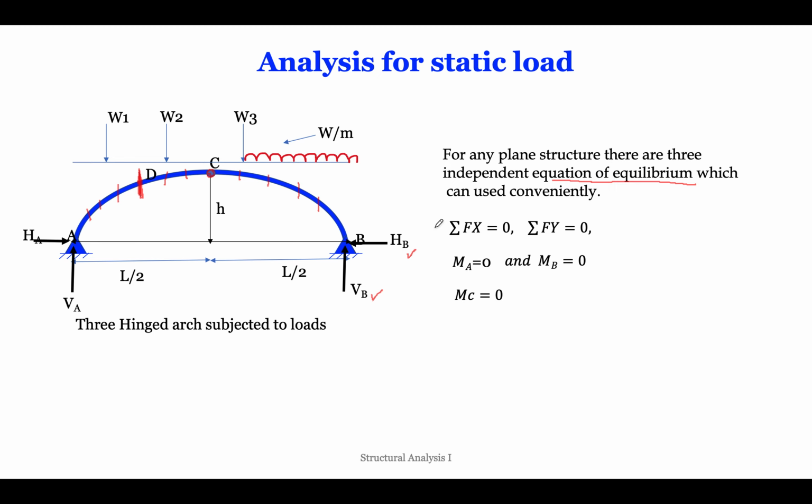For a statically determinate structure, we have three equations: summation of forces in x direction is equal to 0, summation of forces in y direction, meaning all vertical forces, is 0, and moments. For this case, moment at A and B is 0, because it is a hinge support, and hinges cannot take moment.